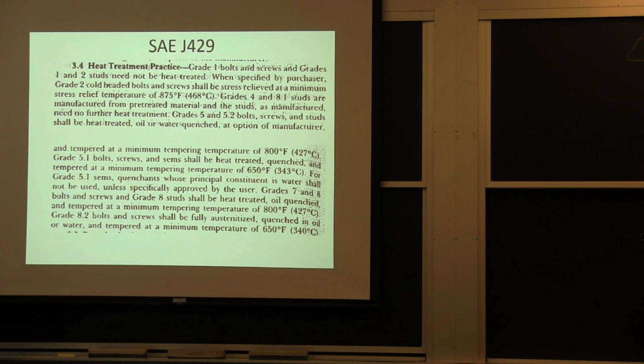I don't know how many of you know this, but a lot of times the way you make a bolt is you start with a rod and you press, you forge the head, and it can be done cold with some consequences. If you really do it cold, you have a lot of residual stresses. You deform the steel in a way that when you let it go, it springs back and you have areas of compression and areas of tension. Now, if this was to go in a chemical environment where stress corrosion cracking will take place and other things will take place, it can happen underground, it can happen in a factory, you could start forming cracks just from the residual stresses.